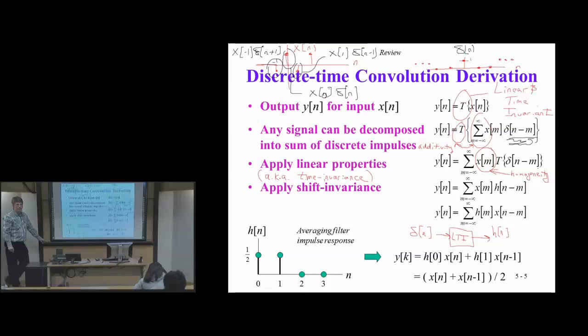There's our convolution formula. In this formula, we're holding x in place and flipping and sliding h about it. We can do a change of variables to get the other form. And this is the form that we need for filtering. So we have a preference. We want to hold h in place and flip and slide. We hold the impulse response h in place and flip and slide the input about the impulse response.